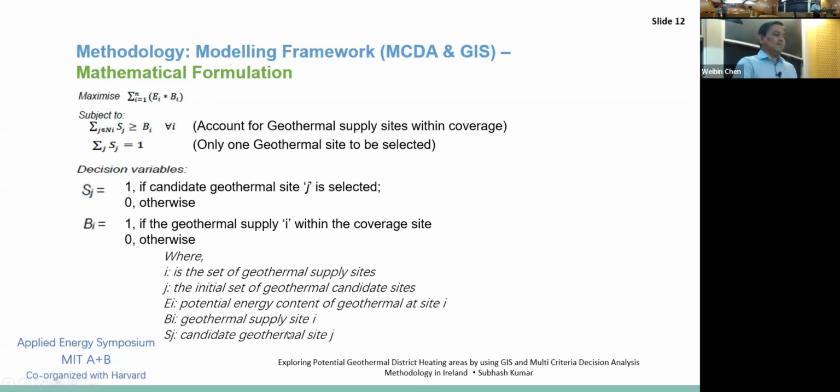Actually, this is the particular location we are locating through the GIS, and this is a function already in ArcGIS. You have to give the requirement, so you have to know what the requirement is in the particular area you want to develop. You have to give the demand actually. The demand can be given to the model, and it can allocate and optimize according to it. If you want to select one area, you can give here, as I have given, S equal to 1, meaning I am selecting one area. But if you are interested in 2 or 3 areas, you have to give 2 or 3 here, and according to the demand it can tell you this location is the most suitable, this is the second location, this is the third location, and so on.